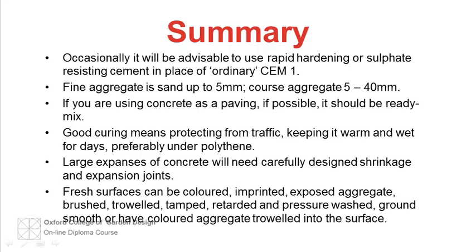The surface can be coloured, imprinted, exposed aggregate, brushed, trowelled, tamped, retarded and pressure washed, even ground smooth and have coloured aggregates scattered on the surface. GRC can be used for lining small water features. The inclusion of fibre reduces cracking and leaks.